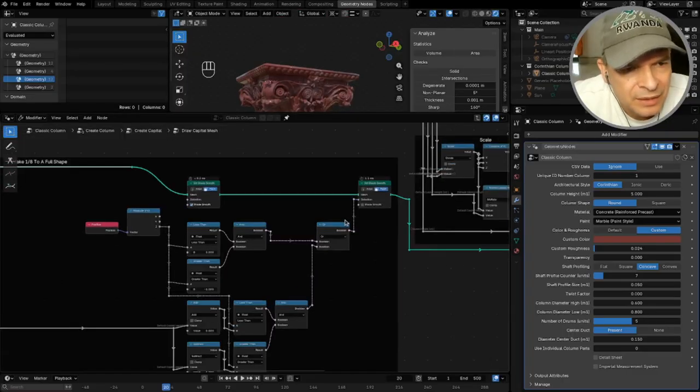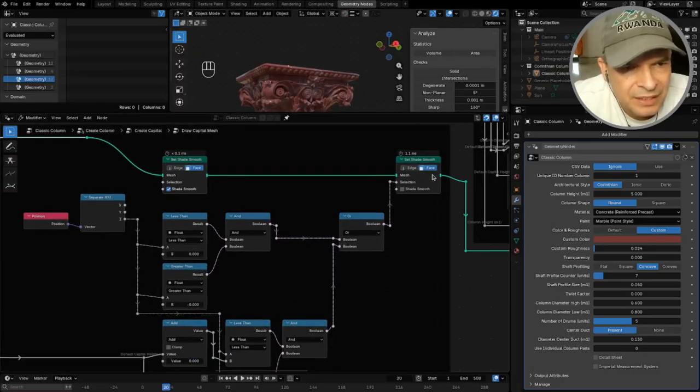And then you can see the shade smooth toggle is switched off here. I select the faces, the top face and the bottom face, and I say, okay, these two you need to shade flat instead of smooth, which you do like this. Only this way works for me.